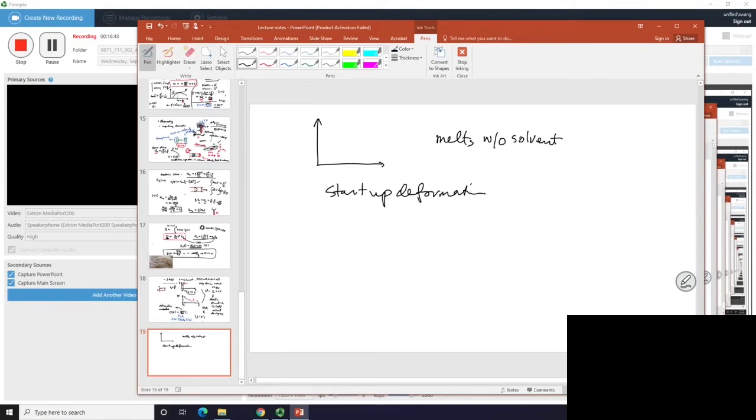I try not to confuse you. If you start with a solution where the solvent is very, very viscous, such that the solvent will just instantly contribute a viscous stress for you, and beyond that there's the polymer's additional contribution, in that case stress will not start from zero. I realize sometimes overgeneralizing has the danger of being misleading and incorrect. I'm only talking about non-solvent melt. Magically, it always starts from zero.